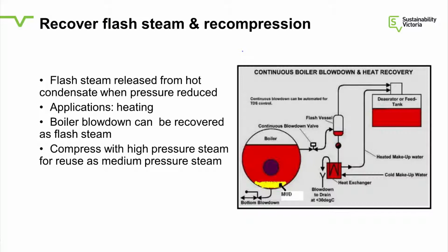They have mechanical vapour compressors where they use the steam to boil off the milk to make condensed milk. The last stage, they take the very low pressure steam that would normally have to be condensed in a cooling tower. They compress that up in a big compressor and they pump it back to the first effect. So it becomes like a big circular effect, and it obviously reduces the amount of new steam that you have to put in to make the process run.